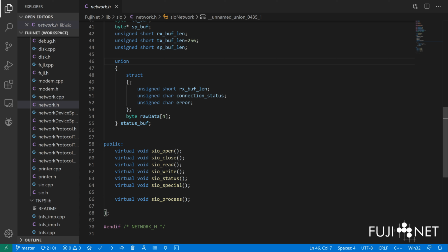And for that, we've allocated 2 bytes for the receive buffer length, which ostensibly means that you can have up to 65,535 bytes waiting to be dealt with. I wouldn't recommend reading or writing that amount of memory, for 2 reasons. Namely, if you're reading that much, you're going to run out of memory long before you ever hit that 65,000 mark.